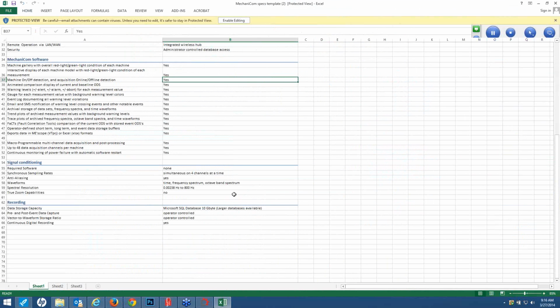So, if you want to look at, for instance, a gear mesh frequency of say 5,000 hertz, and a rotor rotation speed on the helicopter of 3 hertz, and you're getting a modulation of the 5,000 hertz by the 3 hertz rotor rotation speed, can you zoom in to the point where you can see the sidebands? You can see 5,003 and 4,997.